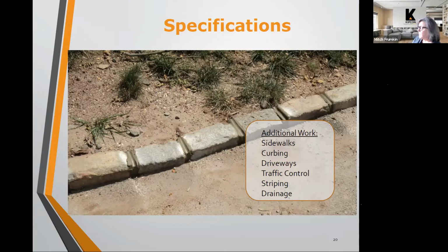If you're going to do driveways as part of an asphalt project, I recommend that you do the driveways first and then do the roadways, just so that you don't have heavy equipment driving in and out over your brand new roadways. That would also go for the same if you're going to do roofing or any other kind of project that might require heavy equipment, that you get those projects out of the way first before you redo your roadways, just because the residential roadways are not meant for heavy construction loads to constantly be rolling back and forth over them.